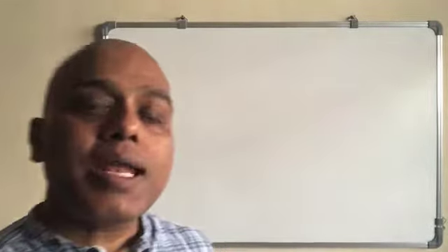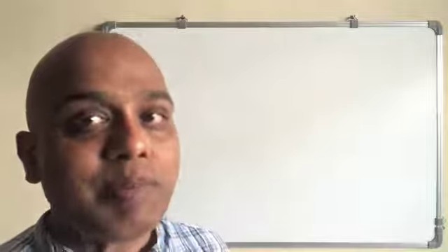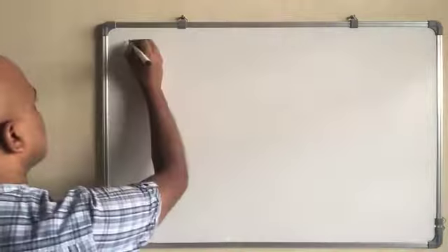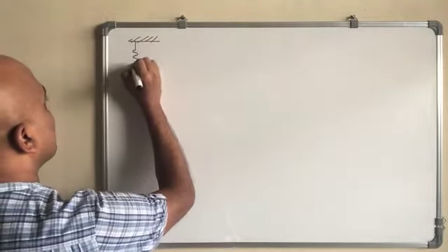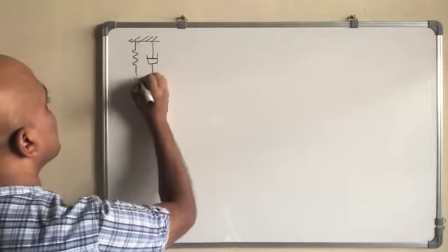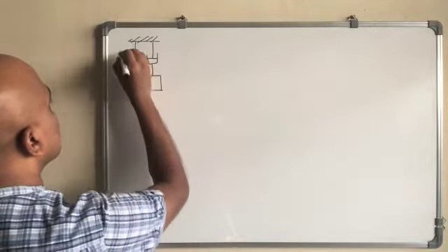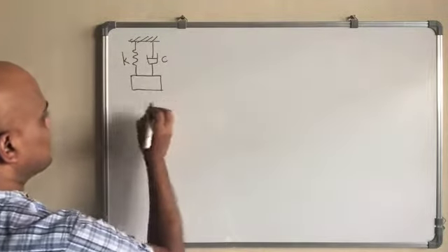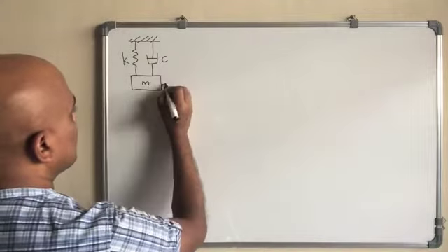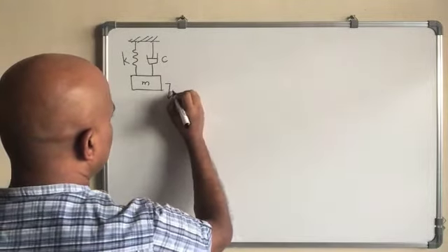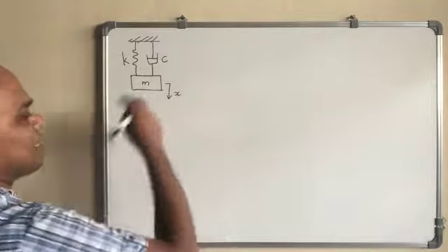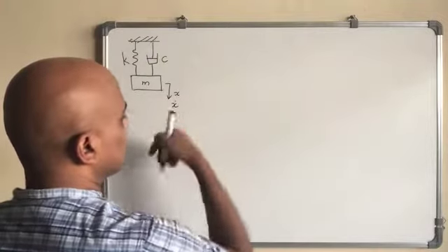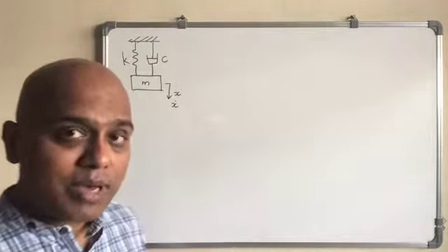And similarly, we can solve the damped problem as well. So our equation for a damped problem, what we mean is we have a spring here, a stiffness K, then we have damping coefficient of the damper C, and then this mass here, which is, let's say, oscillating. This is the deflection or displacement, and it will have velocity in this direction positive, and so on.